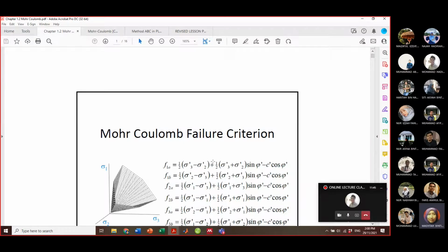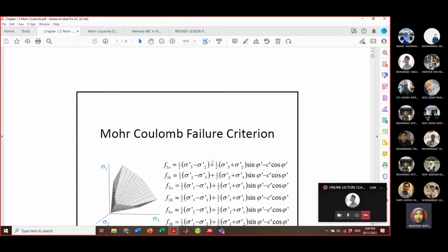For example, why you are exposed to this topic is due to some of the part in numerical modeling in Plaxis, where you need to assign the material or behavior of the soil. So by clicking the right constitutive soil model, either you have linear and then the Mohr-Coulomb, or the Drucker-Prager, or a hyperbolic model, or also the advanced soil model. They will tell you exactly what you are going to have at the end of your analysis.